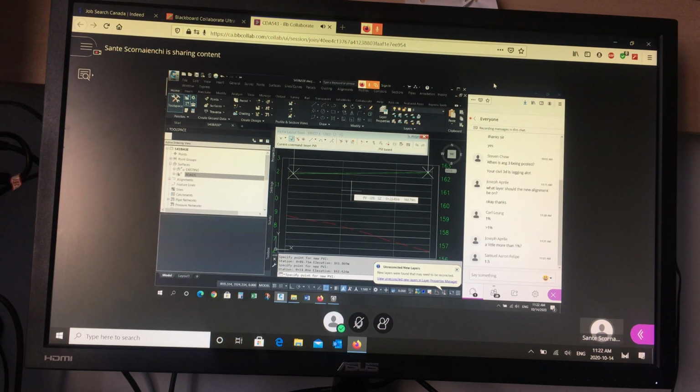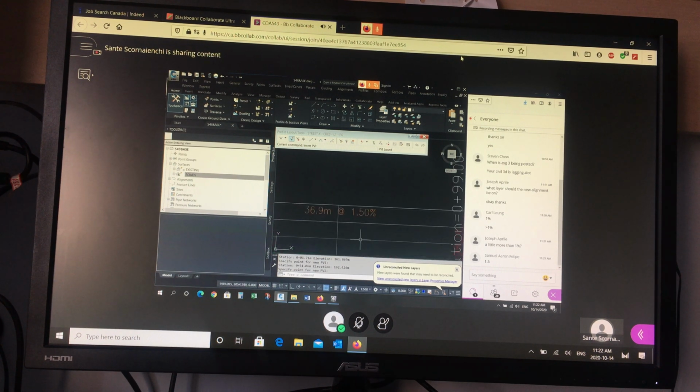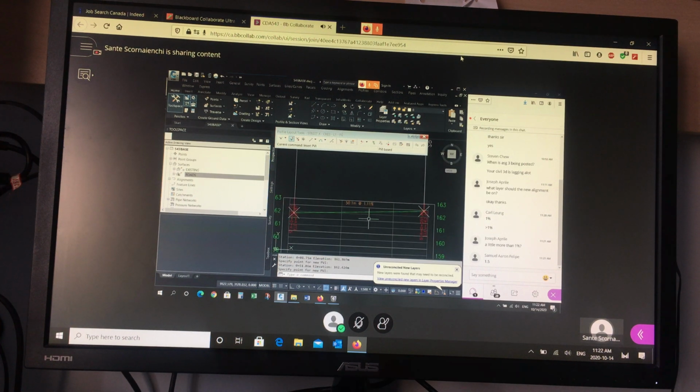Okay, so let me hit enter. And there's the slope, a little bit steeper than 1%. Okay, I hope that you're not saying, wow, that's amazing. It's not amazing. It's what you expect. The reason we designed this to be at 1.5% is because we knew it would guarantee this would be at least 1%, a little bit steeper than 1%. So this isn't really a surprise. It's actually a verification that we did the centerline design correctly.